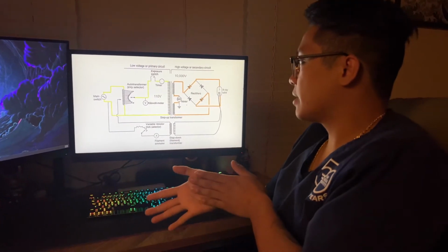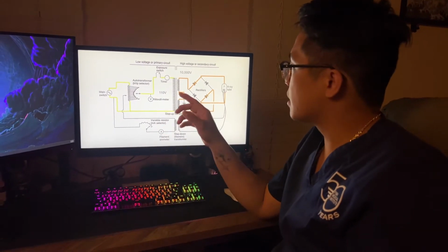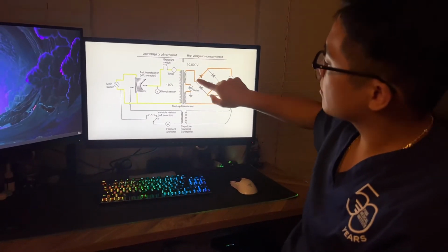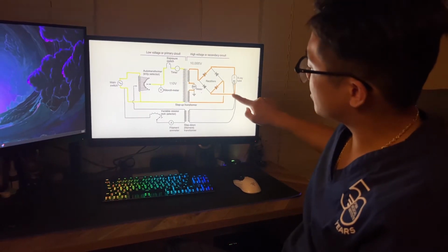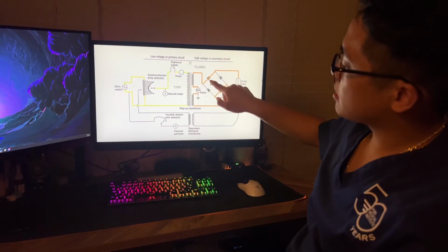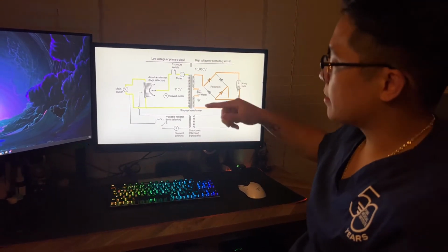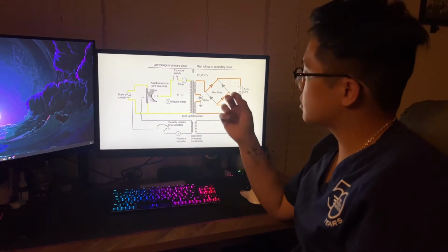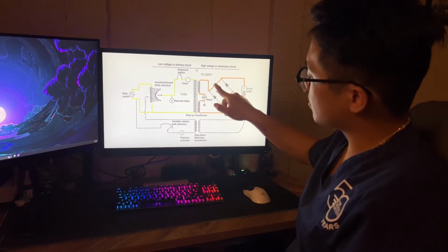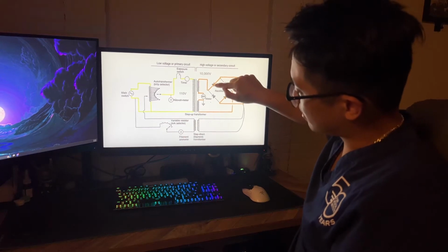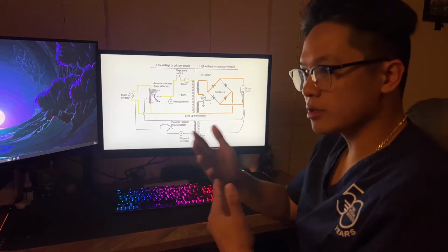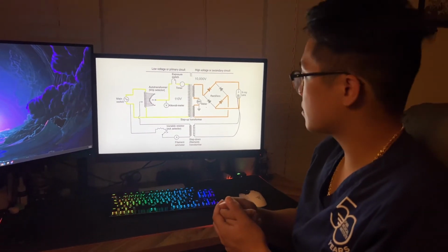As far as the rectifiers, there are two main types, or two main pathways. There's this first pathway where it goes up and over here, follows through, goes down, up, makes this kind of 4 action, and then goes back to that coil. We can see these things right here are called diodes, and one of the main functions of the diodes is to make sure that the electrical current only maintains one direction. Whichever way this little line points is the way it's going to pass through. So it has to continue like this because we don't want anything jumbling up or crossing paths.